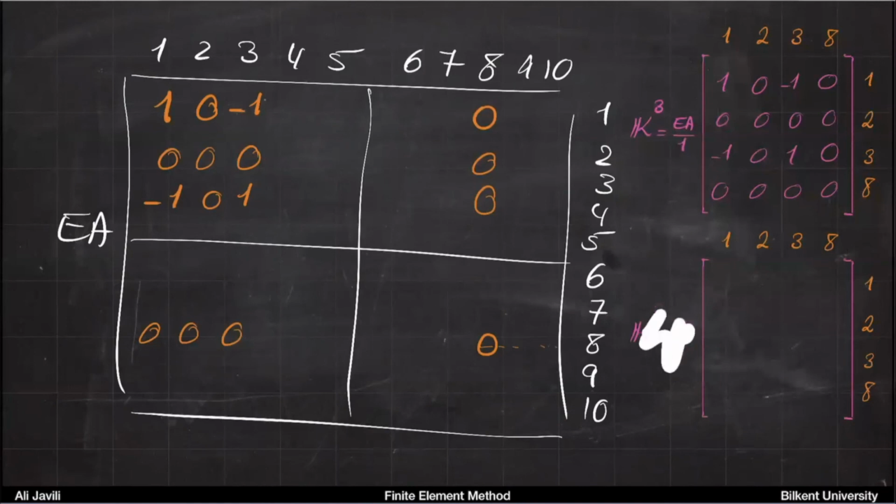Okay, so this thing is going to the 1, 1. Let me write it as a 1, 1 of the global matrix. This is 2, 1. Or I can write it as a subscript so that it looks more familiar to you. I like the superscript because we said superscript means global degree, but just think of it component-wise for now. So this is first row, second column, first row, third column, first row, 8th column of the, let's say these are the global matrix.